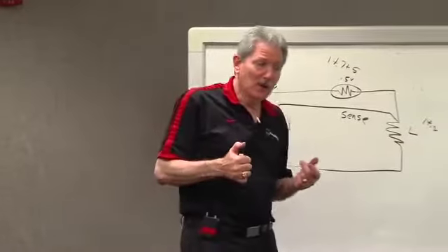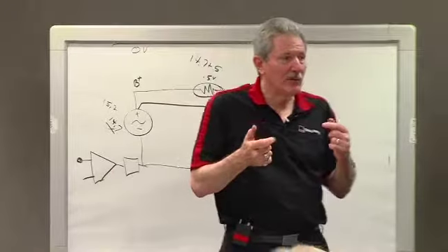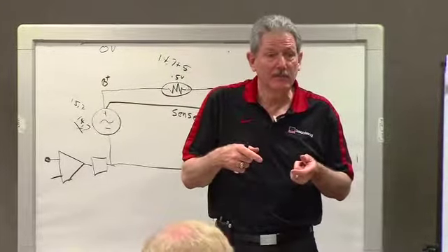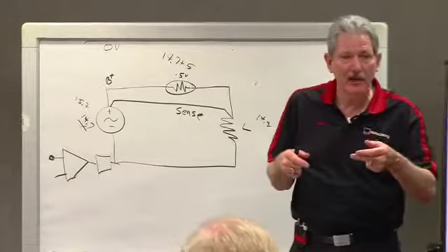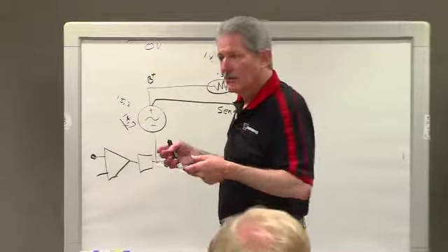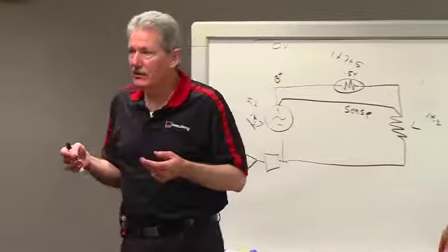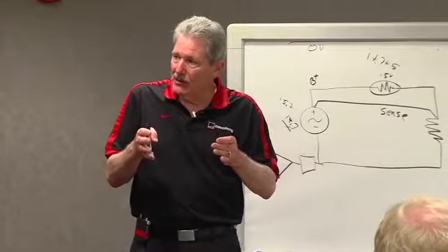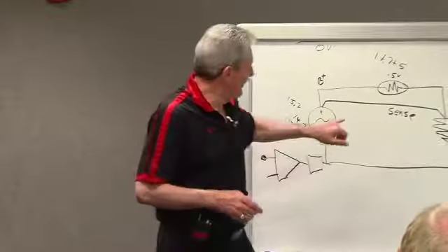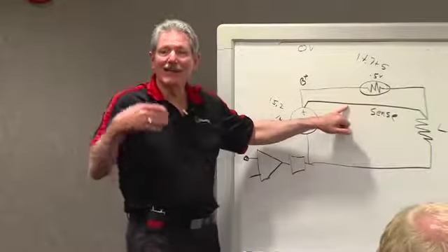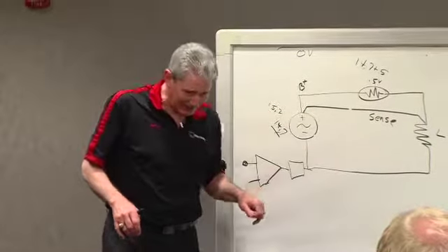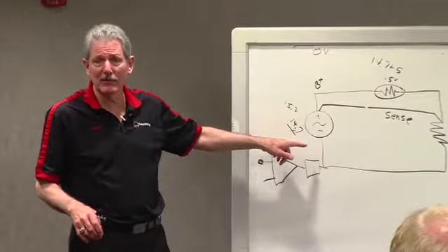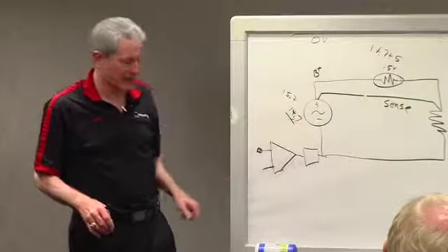Now, what Delco Remy wanted was something that would switch automatically, because now we can deproliferate. Part numbers cost money. So the first 9SI, or CS130, had internal or external sense. If the external sense is connected, it's used. If it's not connected, it automatically reverts back to internal sense.